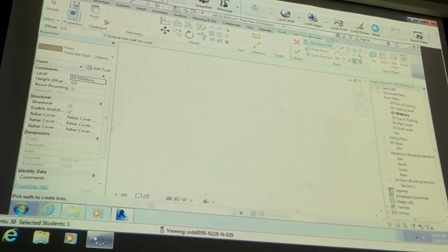So this one here, if you take a look at the sketch, basically the easiest way to start this would be to zoom in at this column here at intersection at grid 5. So go to your line drawing tool here. And maybe start by the top corner of the column. Then draw down to the next column corner here.